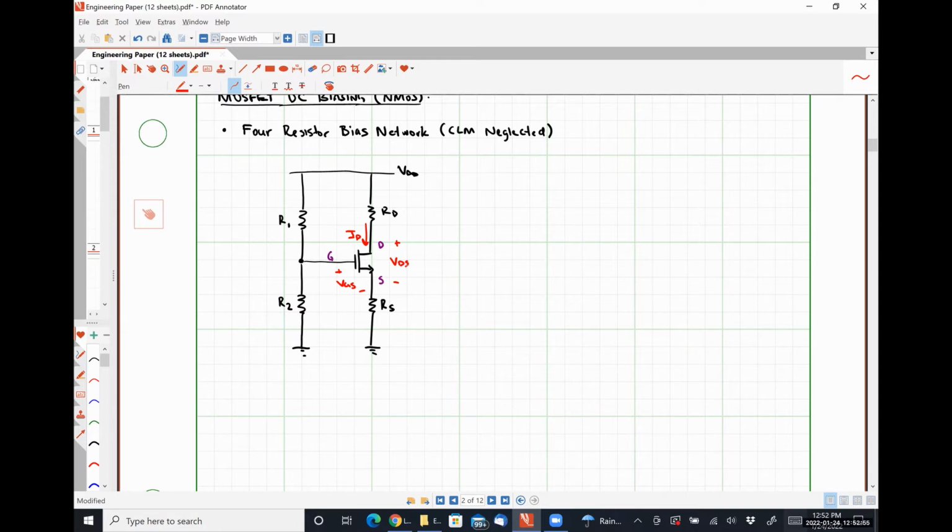So we are going to have to make an assumption. We're either going to have to assume that the device is operating in the triode region and prove that assumption right or wrong, or assume that the device is operating in the saturation region and then prove that that assumption is either right or wrong. As it turns out, the analysis for the saturation region is a little bit easier because there's only one unknown quantity, VGS, right? So we don't have a dependence on both VGS and VDS simultaneously. So we're going to start by assuming that the device is operating in saturation mode.